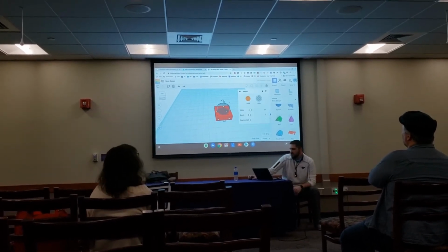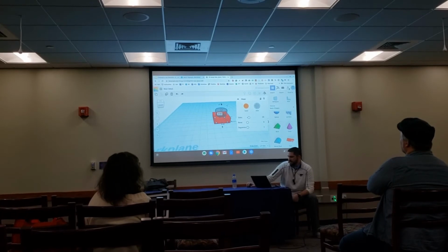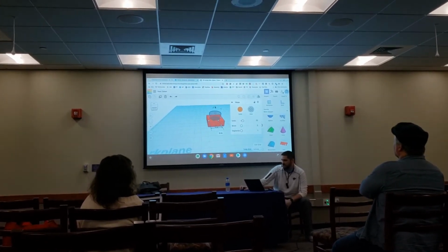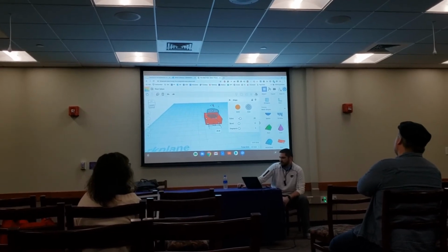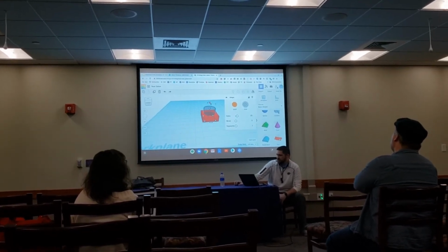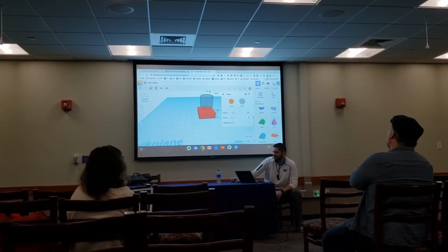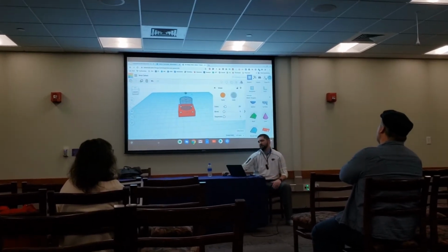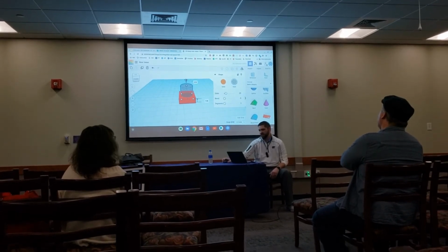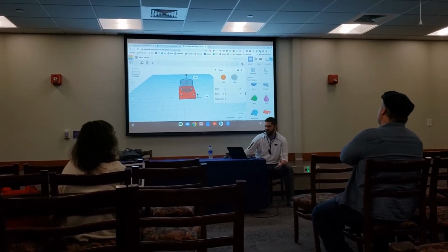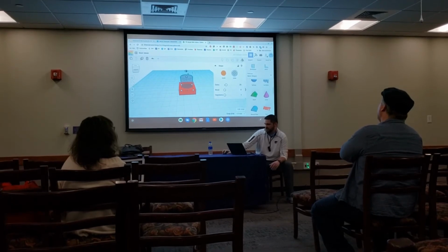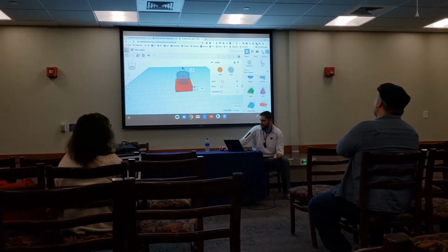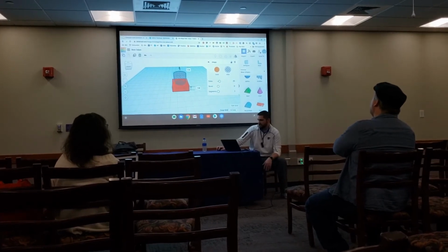So, to manipulate the objects, there's your normal resizing squares around here. To lift it off the work plane, there's this cone at the top where we can lift that up and down. One of the things that kids learn the quickest in Tinkercad is measurements. You have to be able to look at your measurements and dimensions. As I'm raising this up, you can see that dimension at 7 right now on the side. That's telling me how high this object is off the work plane.